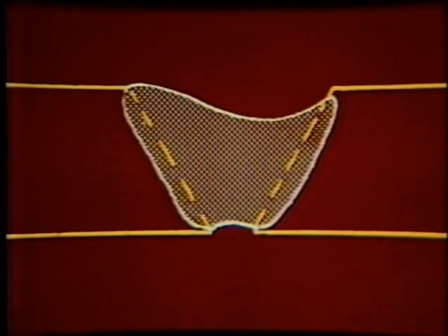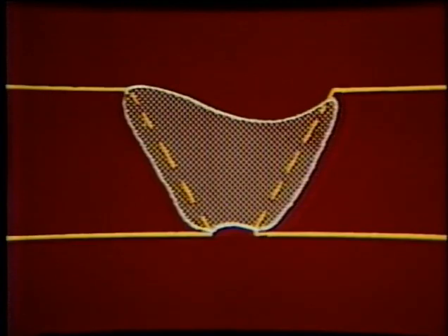The third common profile discontinuity to be discussed is underfill, the lack of sufficient weld metal at the face or the root. In multiple pass welds, an improper sequencing of weld beads will prevent the joint from filling properly, resulting in an underfilled face. On fillet welds, the face will be excessively concave, resulting in a reduction of the throat area of the weld below the designated size. This creates weak points and potential failure. Underfill may also be present on groove welds on either the face or the root side.